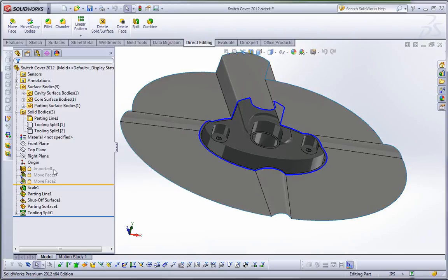This is also going to be useful for complex sketches. So if you've got a logo or something that's an extruded feature that you know is going to be fairly static, and you don't want to update it, or you don't want to go through the rebuild time every time you do a rebuild, the feature freeze will do that. Now, should there be a change, it does flag you.